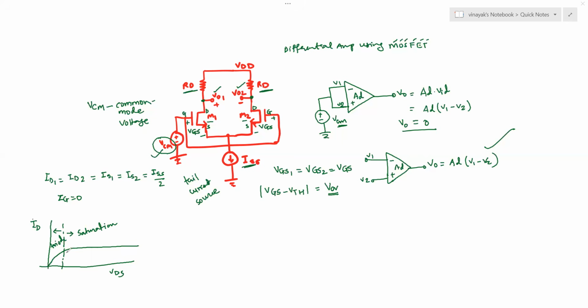Okay, and this is your cutoff point where your transistor enters into the saturation or the linear region. So this you can call VDS minimum, and based on that you choose a point where you say, okay, this is going to be my desired ID, and this is going to be my desired VDS. That's my Q point or the bias point or the operating point of the transistor.